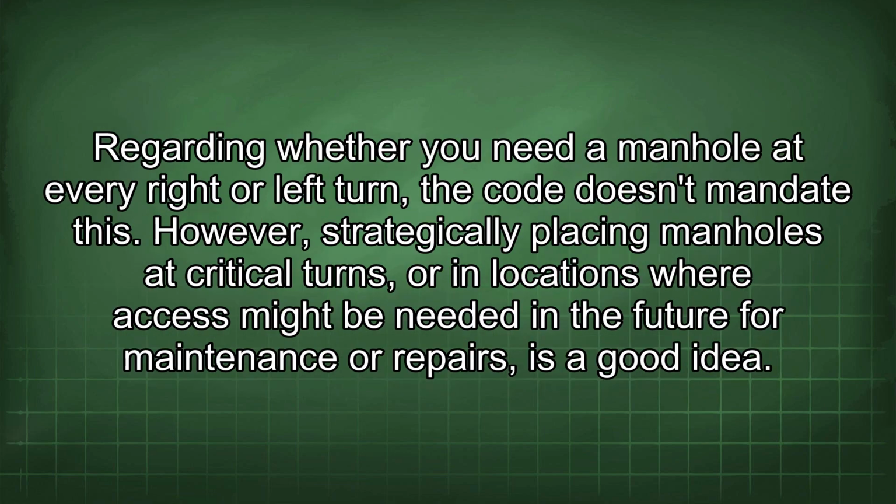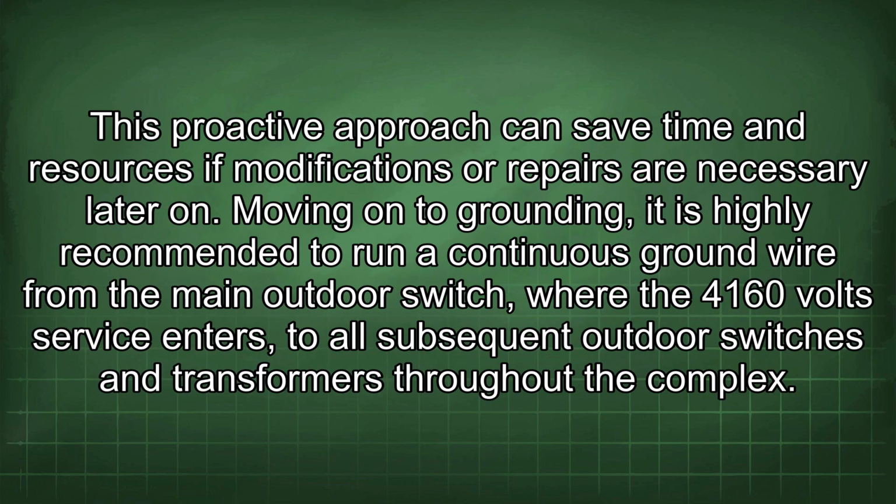Regarding whether you need a manhole at every right or left turn, the code doesn't mandate this. However, strategically placing manholes at critical turns or in locations where access might be needed in the future for maintenance or repairs is a good idea. This proactive approach can save time and resources if modifications or repairs are necessary later on.